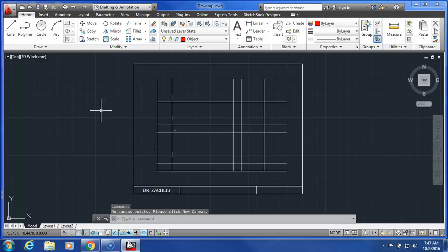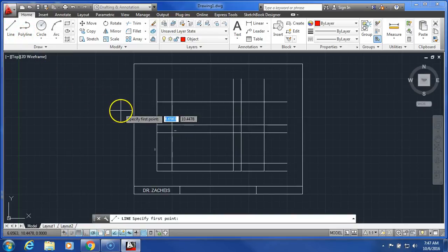Okay, and what we're going to do with this is just trace in over the drawing. Now, again, on your sheet, it gives you 2 of the drawings. It gives you the top view and the front view. We are going to complete the side view. All right, so what we're going to do is let's go ahead and get a line. So you click on a line here. Let's trace in the top and the front view because those are what you already have.